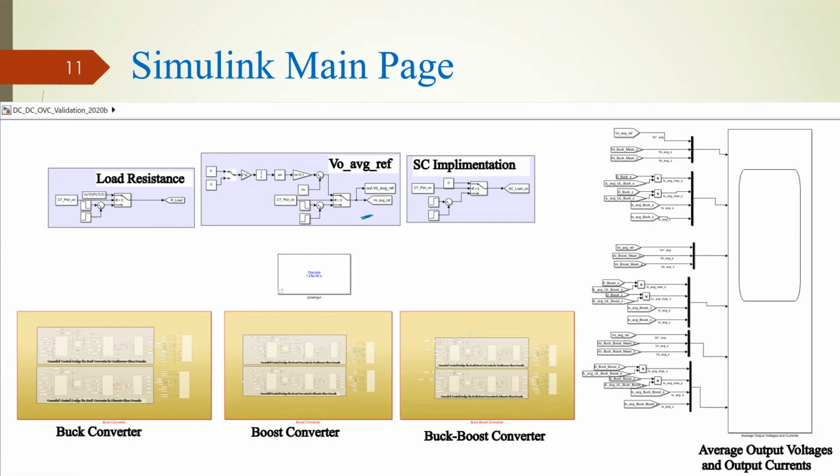This block generates our reference voltage. In the step time response, basically the sine part will be 0, and we give just a step value as the reference voltage. When we want to get the Bode plot, we give a sine reference, since we would like to add some harmonics. So it will have some DC, and then some AC, and the magnitude of the AC is 10 times the magnitude of the DC. It will be like this, 2 pi F into T, and we change F over the range you saw. So it's basically this value.